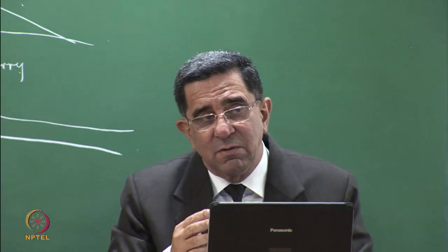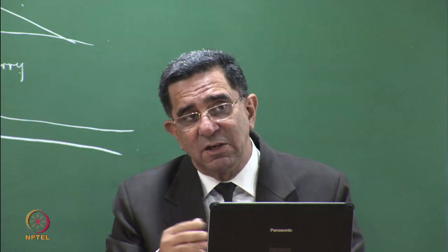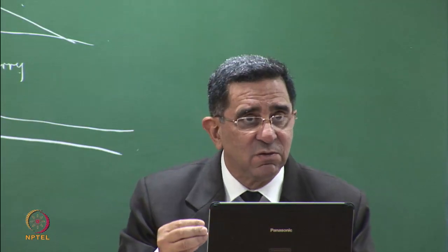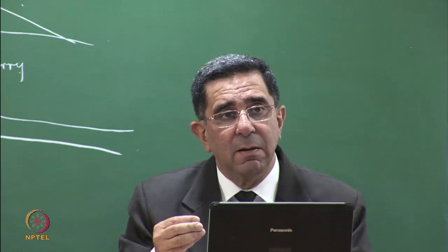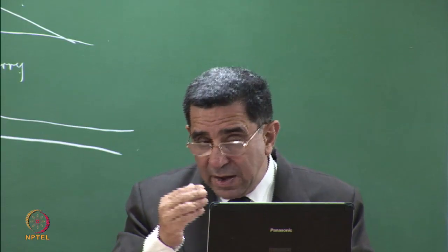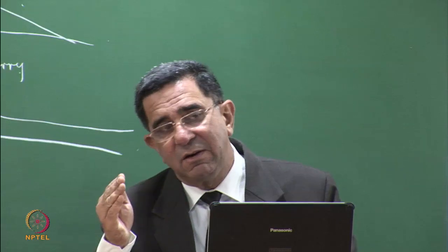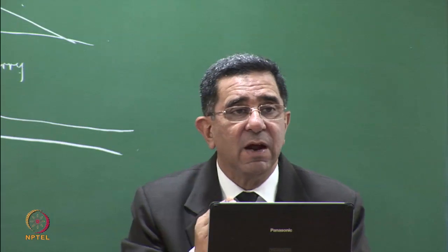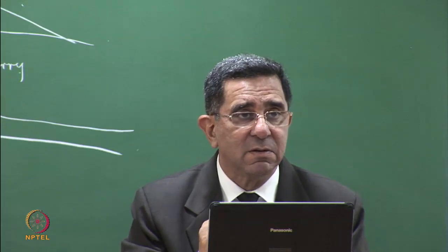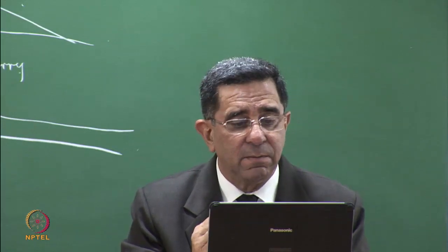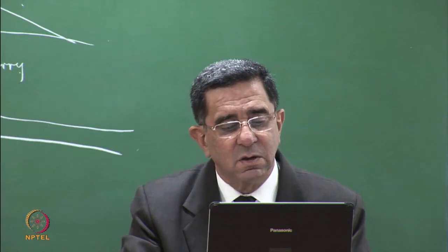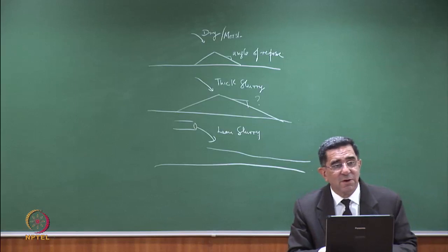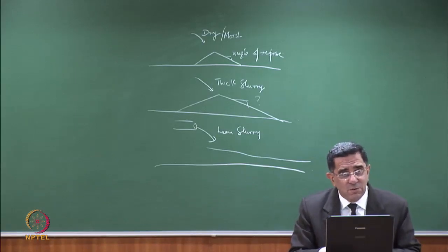In sands, sands and silty sands where there is no liquid limit, there also you will have to be well beyond the saturation stage for the material to behave like a paste. When I bring the water content to 10% or below, then it's not going to behave at all like a thick paste. It is going to behave like soil. So how do I dispose this? It's the same problem. You are going to get a cone. When you drop it, you are going to get a cone from a truck.